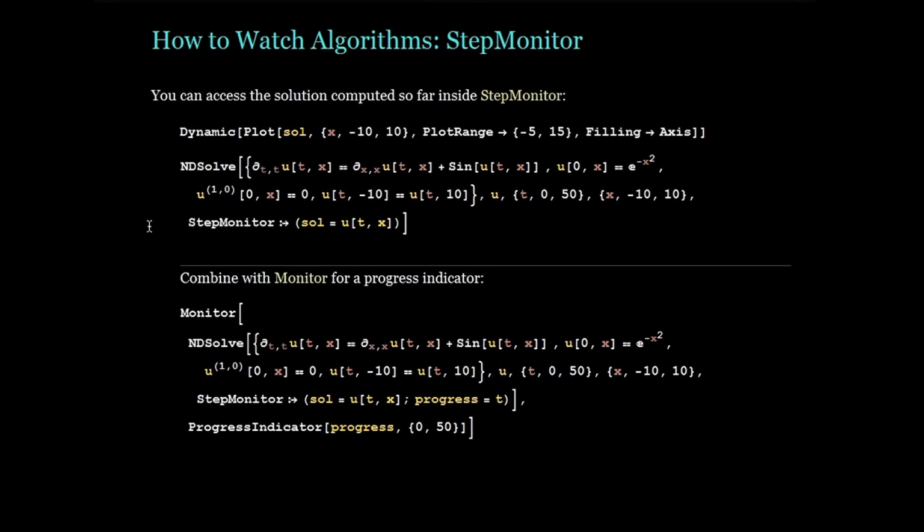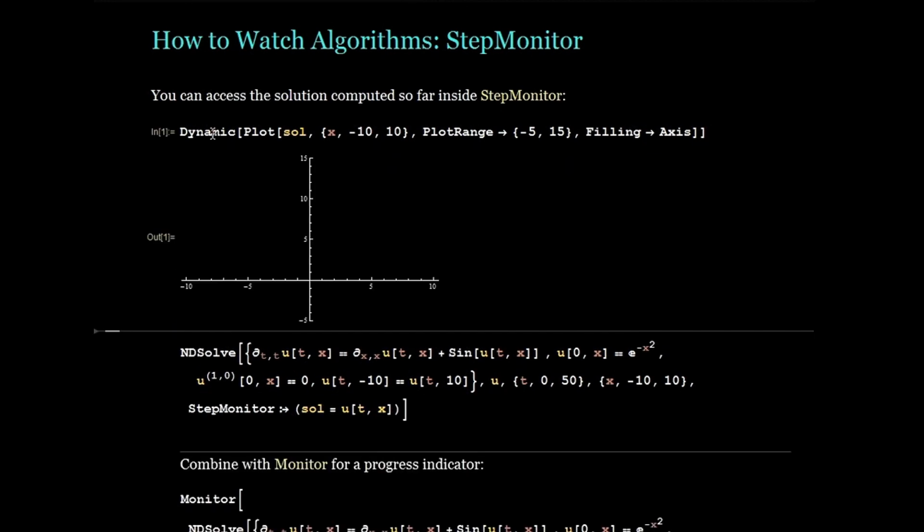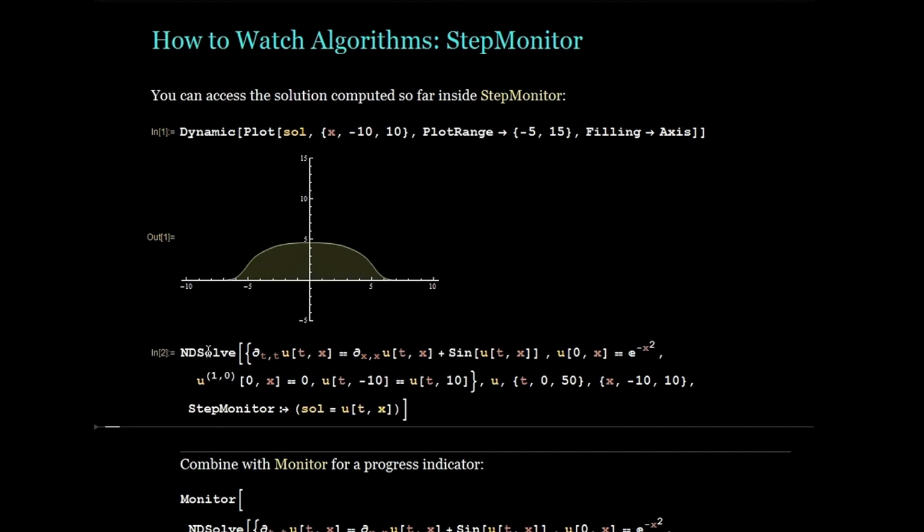One nice way to use StepMonitor is to monitor and visualize the solution obtained so far to a differential equation or other problem. In this example, we'll create a dynamic plot of the current solution of a differential equation stored in the variable sol. Initially, sol is empty, so the plot is blank. But in NDSolve, at each step, we will set sol to the current value of the solution. The result is a live plot showing the current state of the simulation as it proceeds.